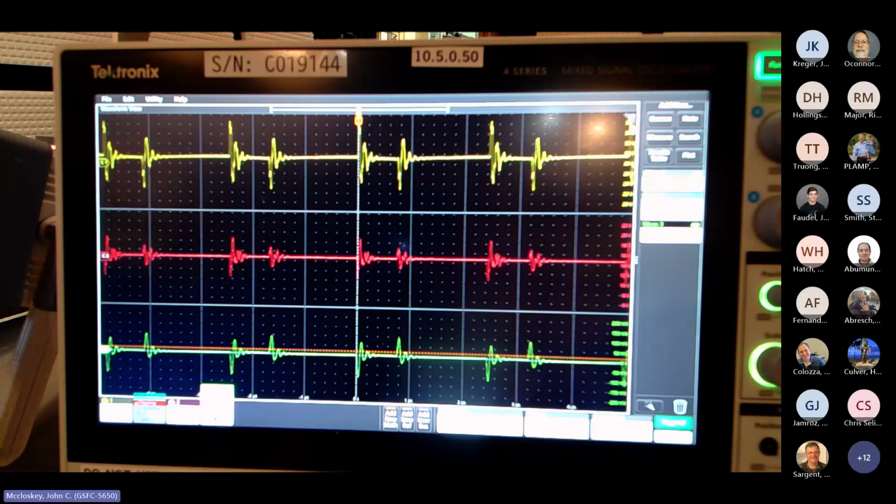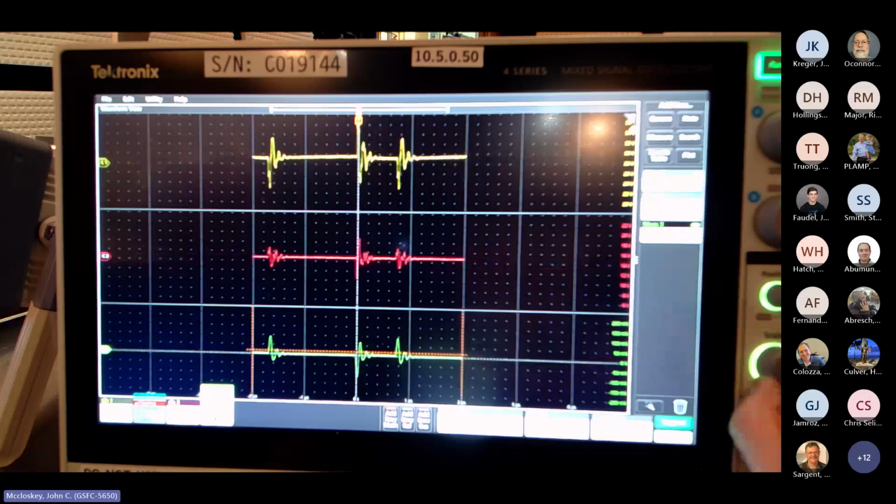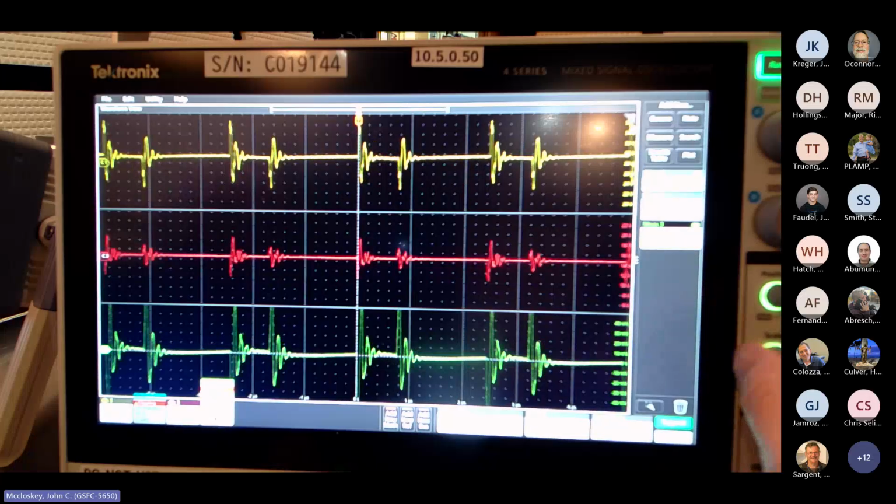And so we'll go ahead and set this up for a continuous sweep. I may need to adjust signal levels to accentuate things, but let's let it roll. We'll set it for auto, so when it hits the end, it'll wrap around and start over again at 10 kilohertz. So there's not much yet. At low frequencies, there's not much current getting through. I'm going to expand that a little bit. When I did this yesterday, it was up at a couple megahertz, I think, when you actually started seeing anything.